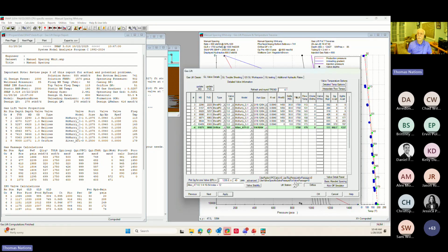A gas lift valve is a fixed volume pressure chamber. Inside that bellows, inside the dome of the valve, we have a nitrogen gas in there. As the temperature changes, that set pressure will change. So we set the valves up in a workshop at a fixed temperature. We have a temperature control bath there that the valves are cycled through and then put in the test rack and brought to set at the exact pressure.